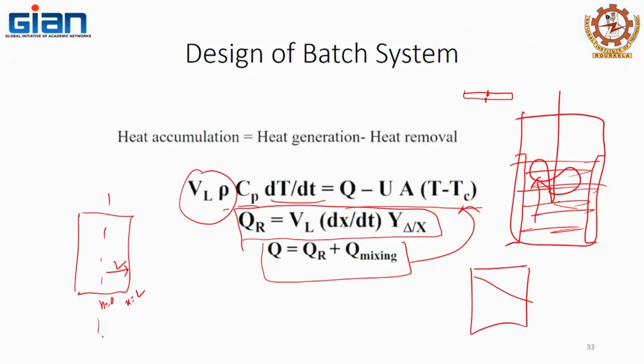There is an equation for forced convection over a cylindrical surface, right, which can be used, that Nusselt number equations. So, those Nusselt number equations can be used if you have a defined geometry of your bioreactor. When you're trying to cool it down or heat it up, you're using those defined Nusselt number equations to estimate the amount of heat transfer. Yes, we can. You're getting my idea or the drift?